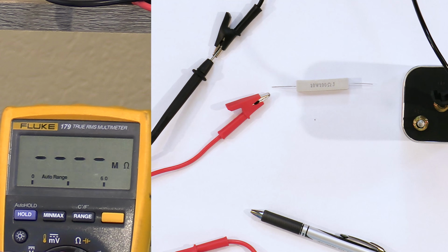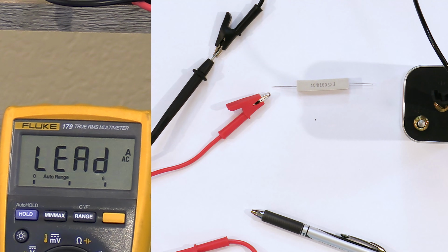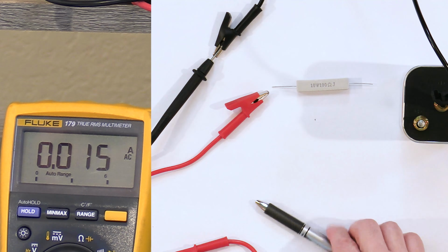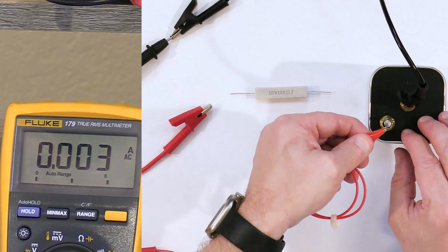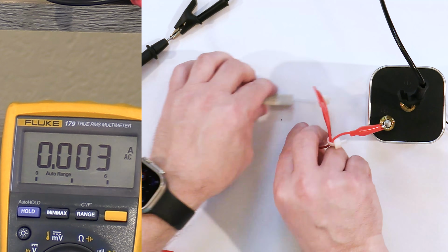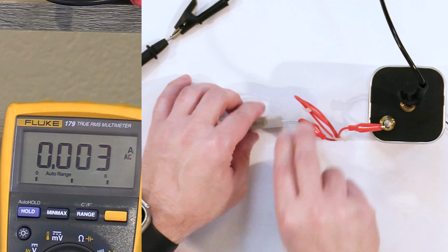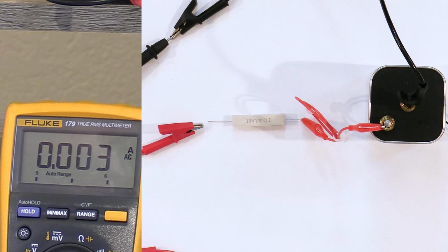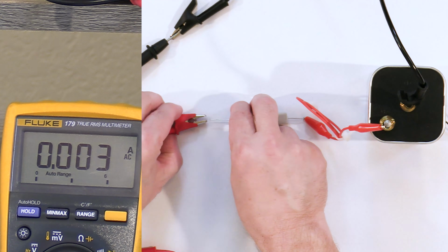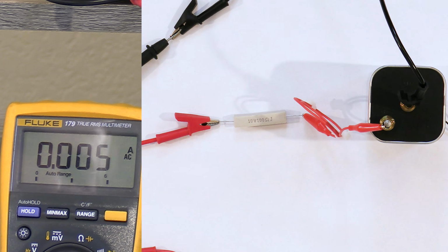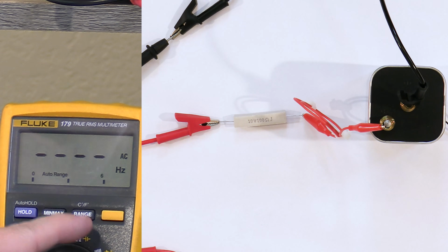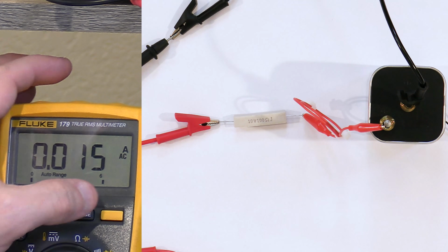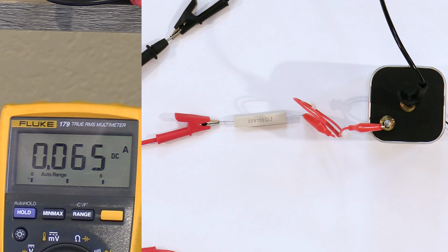And then I've got to switch it over to amps right here. And so now I'm going to connect it to both sides. All right, so I'm going to connect this side of the battery here. I'm going to connect to the resistor right here, and I'm going to connect it over here. So all I've done is connect it in series, where my meter is also in series with this resistor, and I will connect it right here. And I realize for this one, you have to press this button right here. This is trying to measure AC current, so I need to press the button until it says DC.